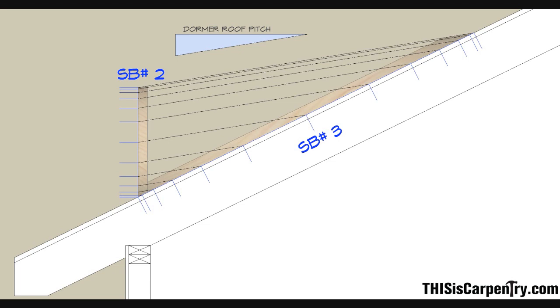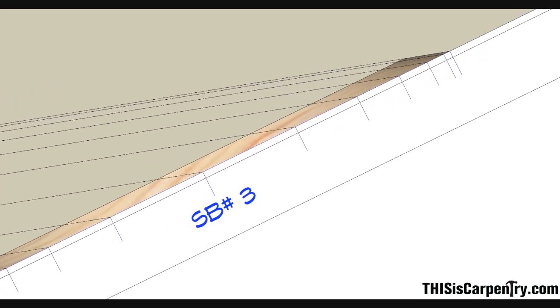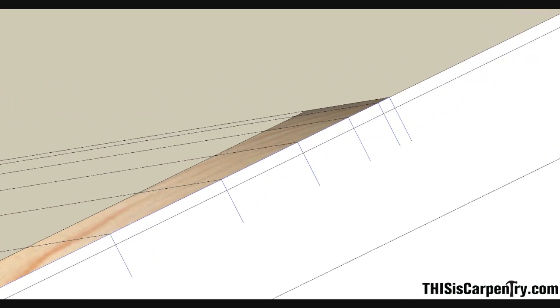Adding the rafters and the valley strips to this drawing will also give us the information necessary for developing the required bevels. Where the 2 roofs intersect at the top of the dormer, a measurement of the valley strip's bevel is made. We'll need this measurement later.